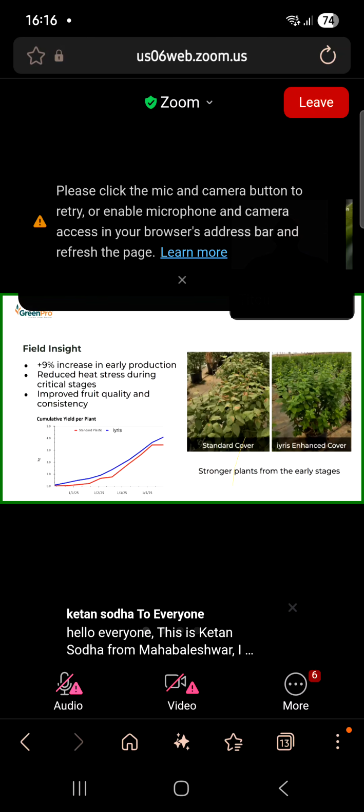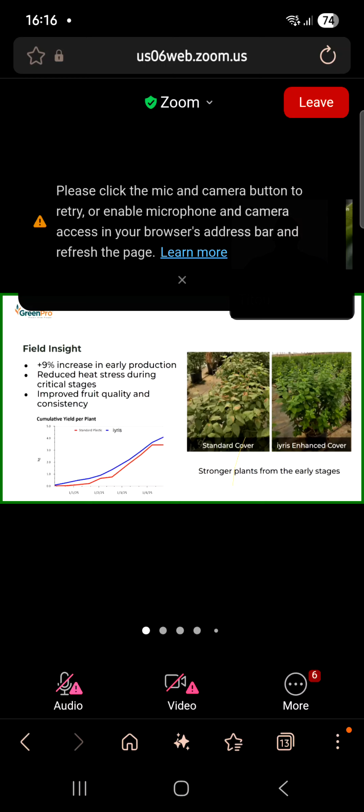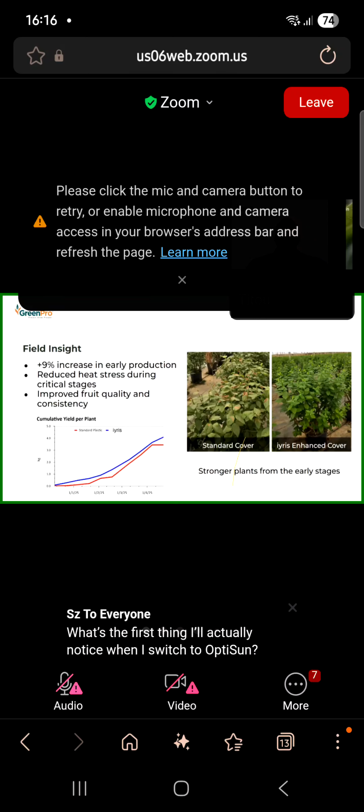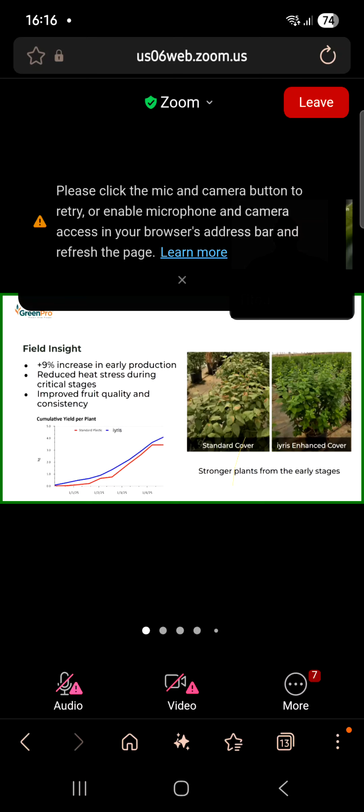Blueberries is an increasing crop for India. There's more and more farms using this. We've got a couple of installations already as well. This particular installation, you can see that in the control we have leaves which are burned, which is actually as a consequence of having to use fogging and misting systems. So even though you're trying to fix for temperature by misting, which in principle is effective, because you have water droplets on the leaves, with the radiation coming in, you end up burning your leaves. So it's a bit of a compromise on the misting system.